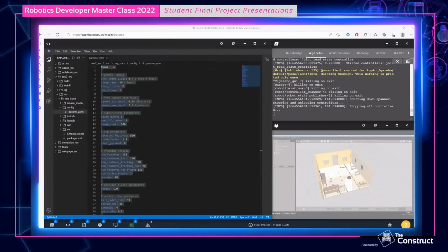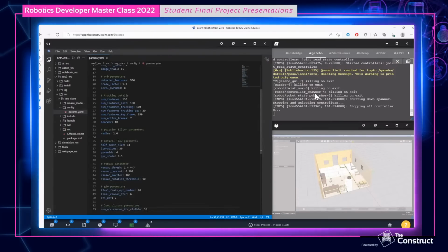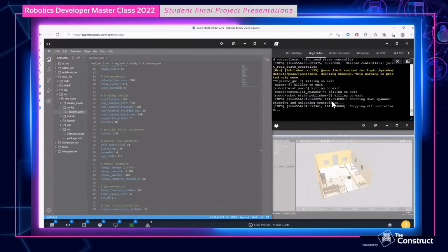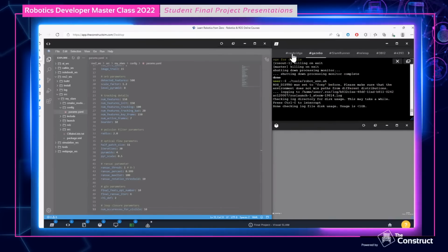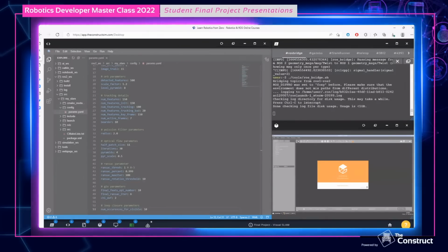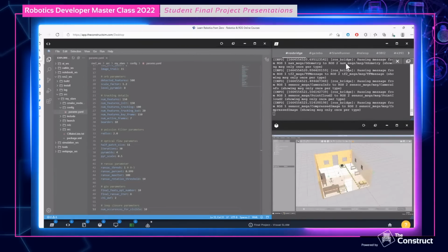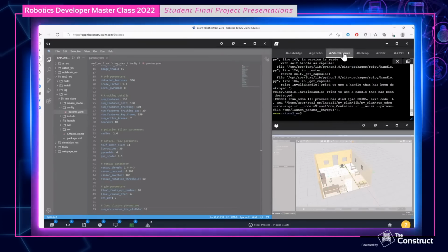Can you plot the images on RViz, so we are sure that the images are being published? Sorry, repeat what you said? So yeah, at the same time that you are visualizing the odometry, can you add also a display to RViz so we can see that the images are being published? So for some reason, RViz doesn't consistently publish compressed images.